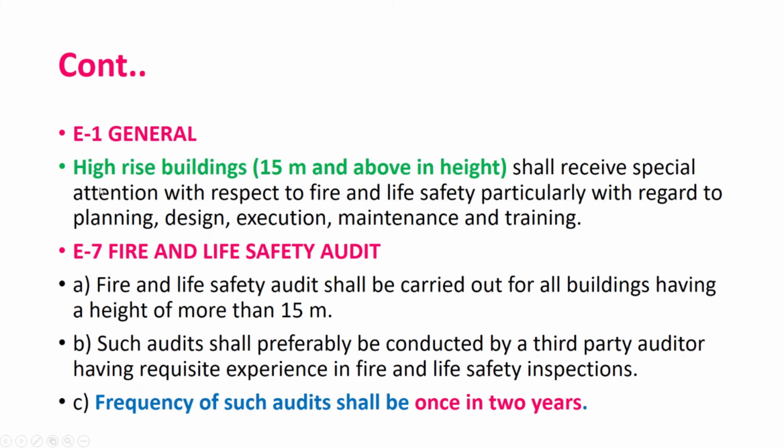Now see the guidelines we have already seen. This is volume 1, and applicability we have already seen. It basically applies to design and construction of the building as such. It also specifies what happens when either a whole or a part of the building is removed. Many times I may be removing a particular part of the building. The code applies to all parts of the building whether removed or not. So it is not applicable to only a particular part; it is applicable in totality. Whenever a whole or any part of the building is required to be demolished, the code applies to any remaining part also.